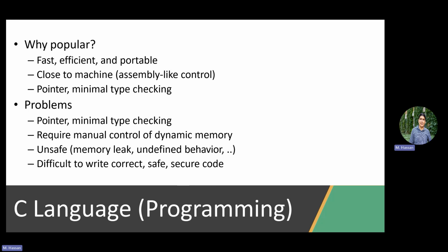Like I go there and say I want to access location 0xFF3F, for example, which is the GPIO register for port A in the controller. No other language enables you to do this. So that's a very big advantage. What is the disadvantage? It's very hard to code and also susceptible to human errors.